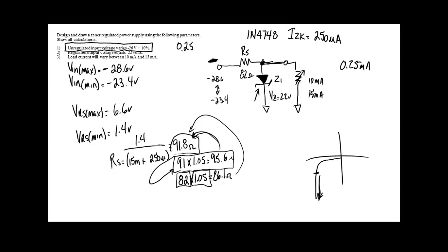Okay. So we've chosen our resistor. And we know two things about the resistor. We know the value and we know the percentage, I mean the tolerance, because we chose the tolerance. What's the third thing we got to do before we buy this thing? We got to calculate the power rating. The watts. So we're going to use V squared over R.